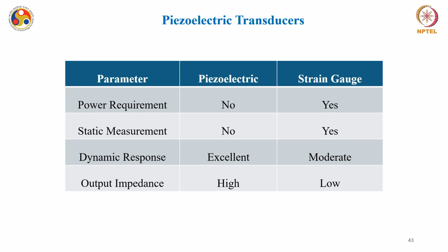Particularly the requirement from the end user. If you see, these piezoelectric devices do not require any external power source, okay. Although they are not suitable for static measurement, their dynamic responses are very good, okay. Although the output impedance is a little higher as compared to the strain gauges, according to the need of the user, a particular kind of transducer can be utilized, okay.